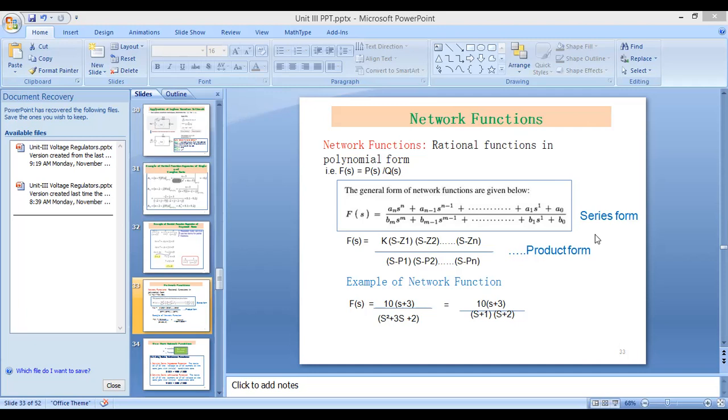These are the hybrid parameter, and then the admittance parameter. Admittance is the opposite of the impedance parameter, because admittance is the reciprocal of the impedance. Then we have seen hybrid, then transmission, or the ABCD parameter. Then inverse hybrid, and inverse ABCD, or inverse transmission. So depending on these four variables, voltage and current for port 1 and port 2, we have 6 different parameters.